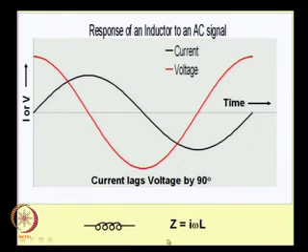Therefore for an inductor, if you send 0 frequency, in other words a DC, if you connect a DC power source to an inductor, it will act as though it were just a wire, current will just flow through it smoothly, no problem. If you send a very high frequency through it, say thousands of hertz, tens of kilohertz, then its impedance will be very high, it will prevent the flow of current through it, it will act as though it is an open circuit. Okay, so this is what we have, and that is a symbol for an inductor.